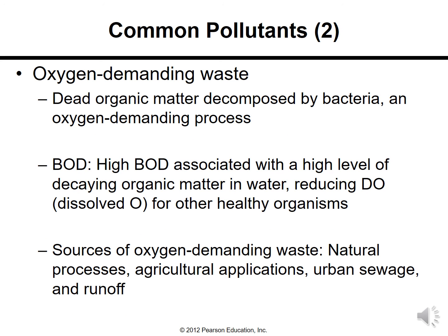Oxygen demanding waste. What does that mean? Oxygen demanding means some waste that really needs oxygen. So dead organic matter is decomposed by bacteria in an oxygen demanding process. When an animal dies, that is organic matter. What does organic matter mean? It is built up of hydrogen and carbon, hydrocarbons. So dead organic matter is decomposed by bacteria that need oxygen to break down this hydrogen and carbon material, and eventually it becomes carbon dioxide and water. That's the end product, but you need oxygen in this process.